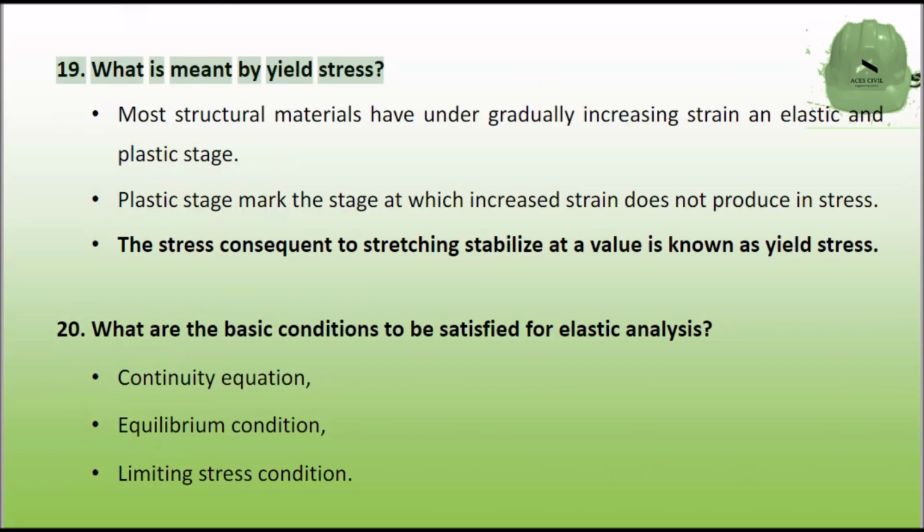What is meant by yield stress? Most structural materials have, under gradually increasing strain, an elastic and plastic stage. Plastic stage marks the stage at which increased strain does not produce an increase in stress. The stress consequent to stretching stabilizes at a value known as yield stress.